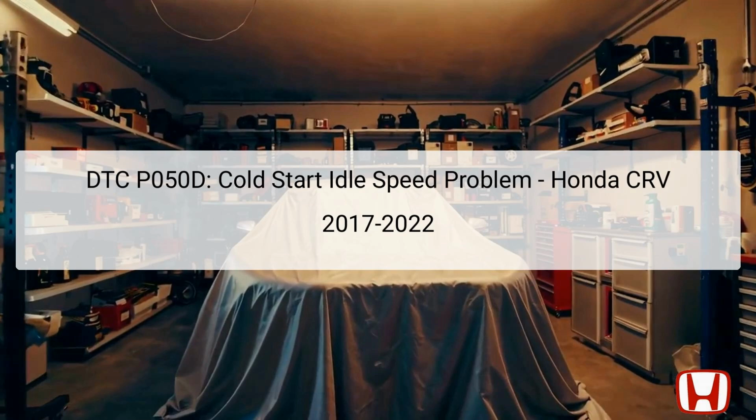The PGM-FI, or Programmed Fuel Injection System, plays a vital role in regulating the air and fuel mixture for optimal combustion. Understanding the core components involved in this DTC, including the IAT, or Intake Air Temperature Sensor, CKP, or Crankshaft Position Sensor, and MAF, or Mass Airflow Sensor, is essential for effective troubleshooting. Let's explore these components and the overall process for resolution.